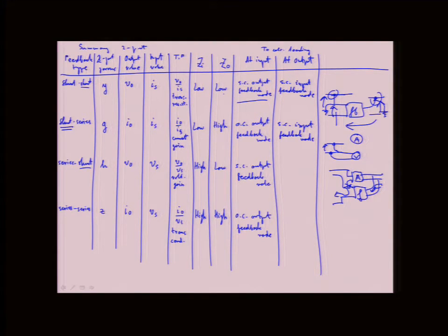Right? Remember, when we did two-port, what that really means is that this feedback circuit, viewed from this side, had this Y22F, right, which was the conductance, and then it had the controlled source, right?